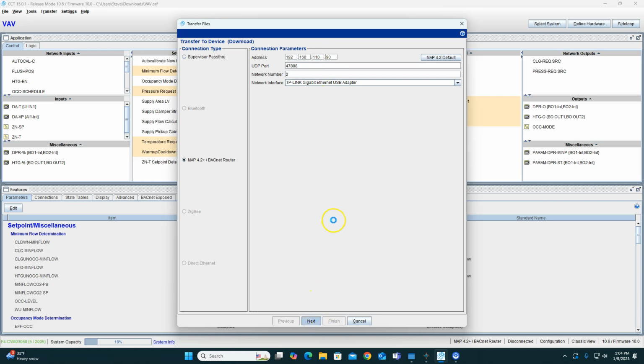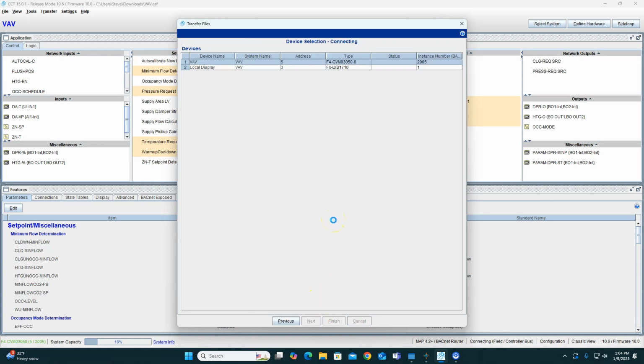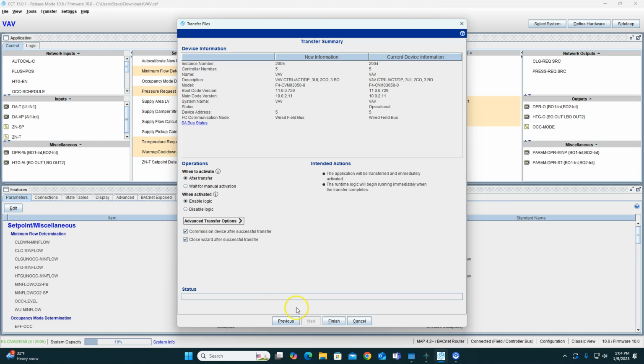Going through my JACE, commission. Now this is going to look funny because I don't have a 1K sensor hooked up to this controller. I have a 10K type 2. So it's going to give me a faulty reading whenever it comes up.